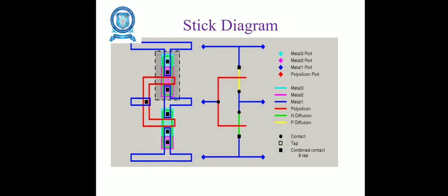Design rules allow the transition of circuits into actual geometry in silicon, and they are the interface between the circuit designer and the fabrication designer. Why do we need stick diagrams in VLSI? These stick diagrams are a straightforward way of recording topography and layer information. They use color codes to represent the layer information. Also, they display all the components and their relative positioning, bring us one step closer to the layout, and aid in the planning of the layout and the route.